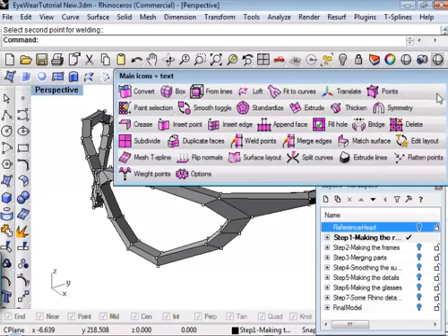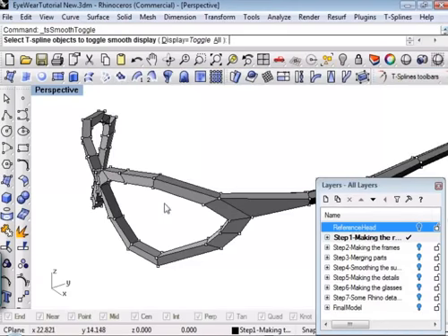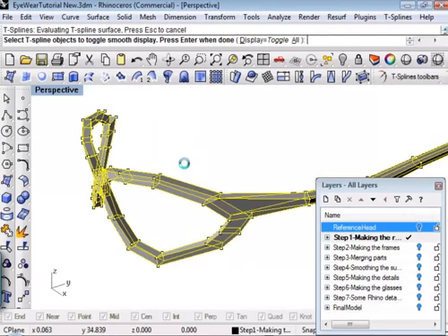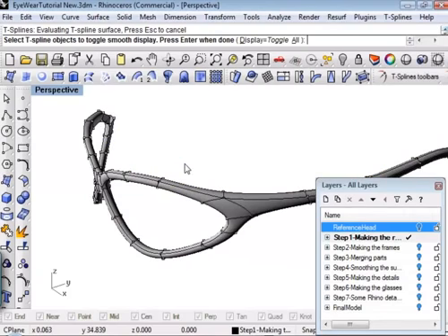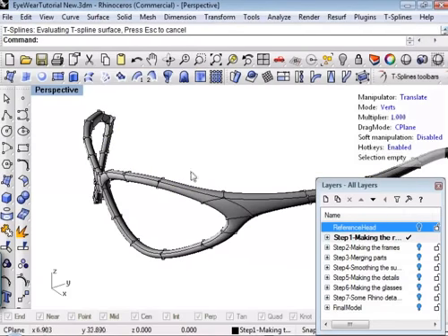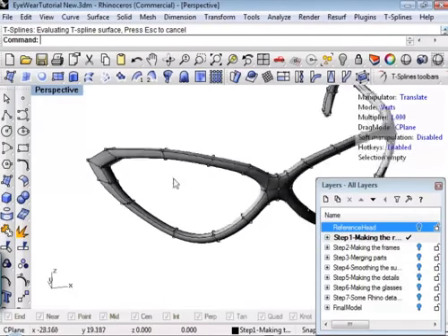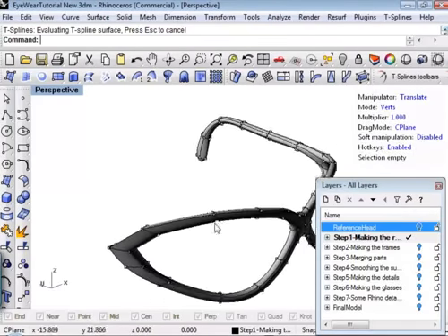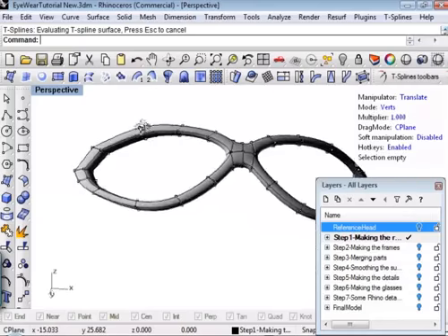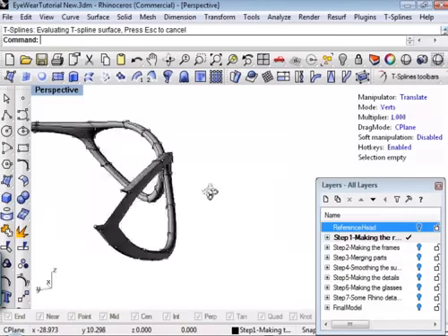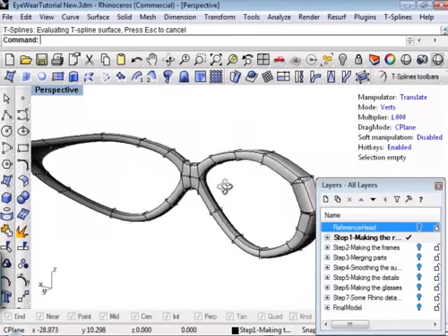This is the stuff that makes new people crazy because it's a little different than what you're used to. If I toggle smooth, the model's going to look awful, which is not what we're going for. Actually, that transition looks fairly good. But you'll notice over here there's all sorts of mess going on. Well, that's because there's a hole over here that's not connected to anything.